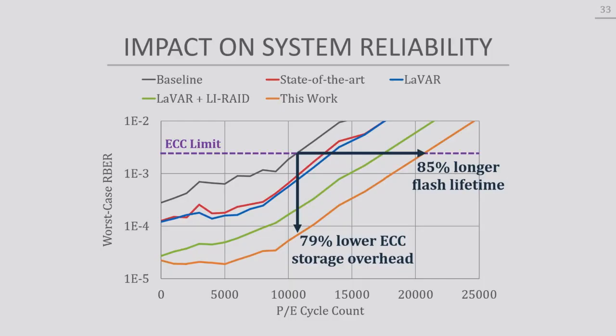So the x-axis is the program cycle, meaning that after you program a certain amount of time, the device is worn out to an extent where you can no longer guarantee that the data you store on it next can still be reliable. Okay, so it's the device. Even if I reset it, it's a device, yes. Even if you reset it and then you program new data, it's not reliable anymore.